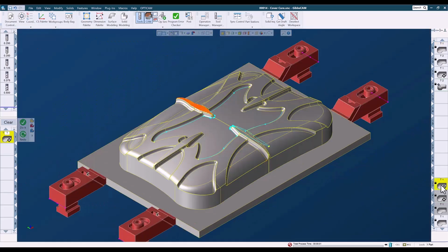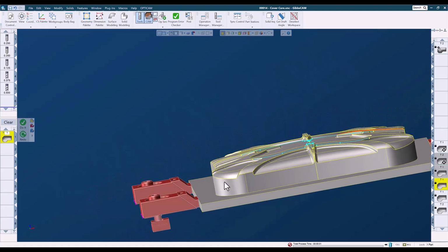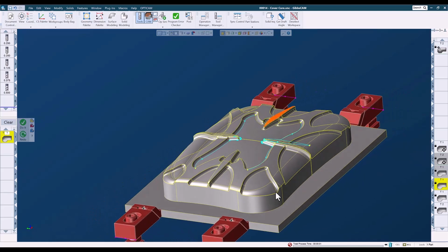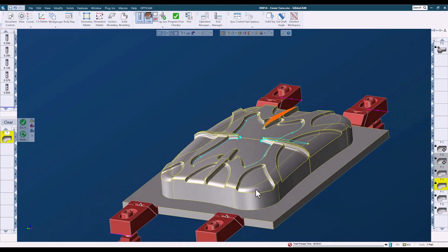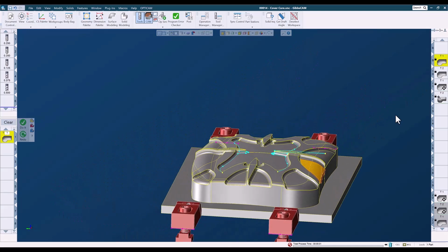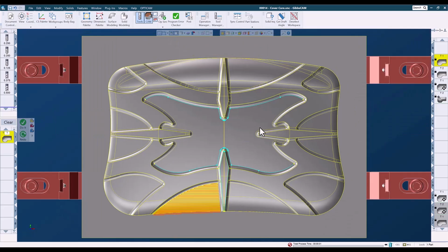Let's take a look at some toolpath. Now, this part's not terribly complex, and in reality, you could machine most of this, if not all of it, with just some simple linear toolpaths, such as lace cut from the surface process. But more than likely, you'd want to machine different areas of this with different strategies, both to improve cycle times by minimizing retracts, as well as selecting toolpaths that better conform to the shape of the area being machined, both to even further reduce cycle time and to improve effective surface finishes.